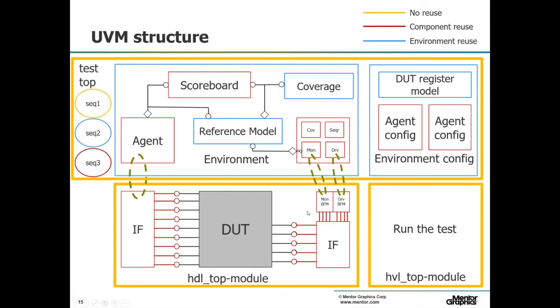So the basic structure of the UVM is that for every major communications port on our device, we create an agent to send and receive transactions over that port. So we've kind of split the test bench into: up here is all at the class level and transaction level. Down here is where we pass those transactions.